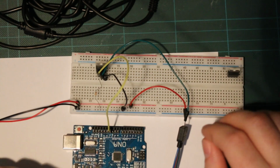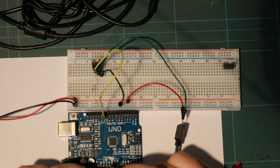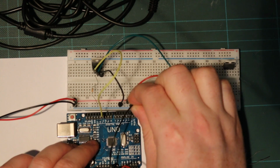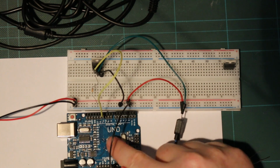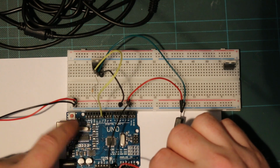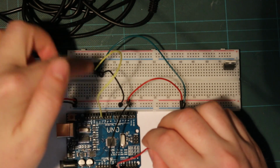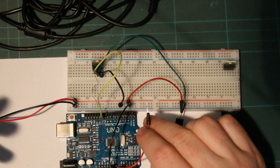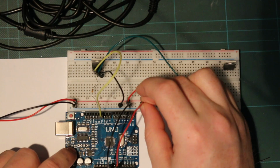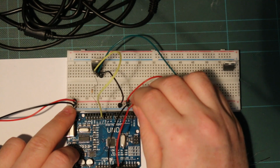Now, very last thing I'm going to do is power this Arduino with this same power source to avoid multiple wires. In general, we connect the ground of the Arduino to the ground of everything else. That's really important. If you were initially testing, which I would recommend the first time you set this up, don't power the Arduino with the same power supply, power it with the 5-volt power supply, and then have this all powered separately. I'm just doing this because it's easier and I know it works. So I'm going to put the in of the Arduino into the 12-volt power supply on this.